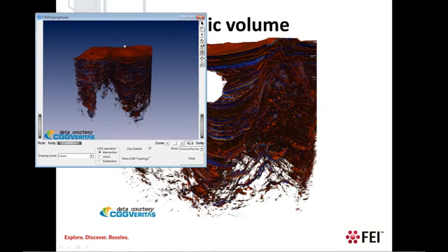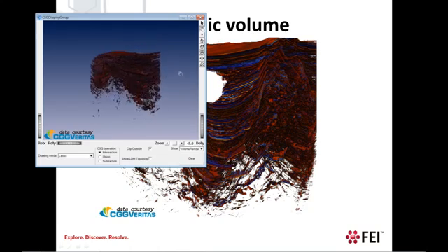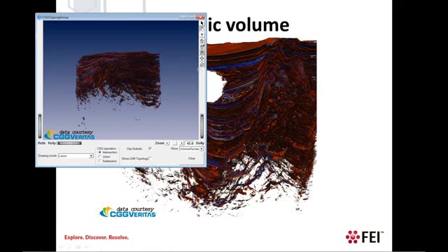For example, I will only keep this part of the seismic. To draw the lasso on screen, I use some built-in Open Inventor tool. Once I release the mouse, the lasso is considered over, and Open Inventor then generates a 3D geometry as the extrusion of my lasso along the camera view. It then clips the volume against it, so we finally only see the volume I selected under my lasso.